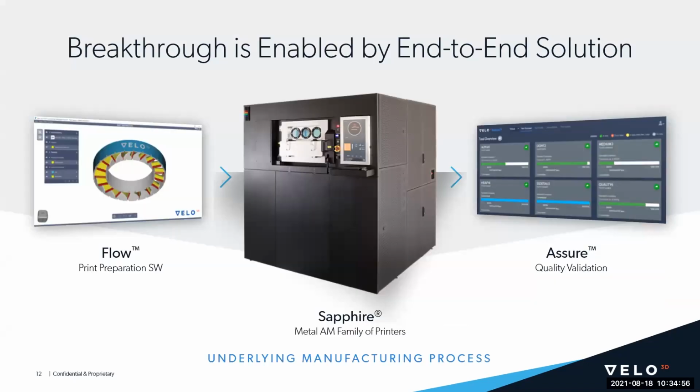So going into what enables us to print a part like that, it's really the product of the end-to-end solution that VELO offers. By end-to-end, what I mean is our system runs from pre-print setup through printing, and then through process control and quality assurance for the printing process. A user starts in our pre-print software, Flow. In Flow, you lay out your builds and you initiate the slicing, which is where laser parameters and laser paths are generated. From that, you get a VELO print file.